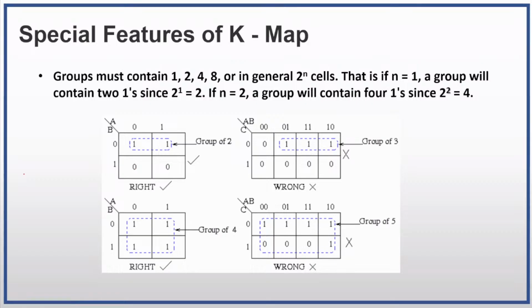So therefore, in this case, how can you group this kind of Karnaugh map? You can select these two, and as well as you can select these two. So the groups can overlap, but always you have to follow this rule. And here 4. So this is right. And in this case you can see that you have grouped 8 inputs, but according to this rule, it is no problem,